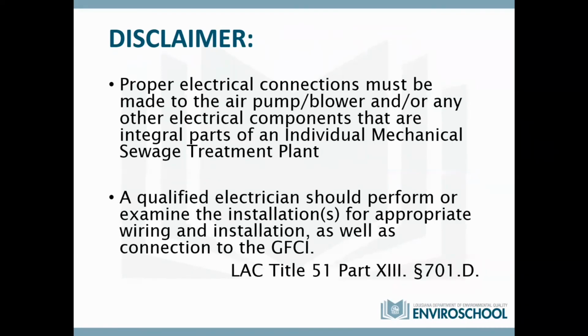And then the Department of Health also says that proper electrical connections must be made to the air pump, blower, and any other electrical components that are integral parts of an individual mechanical sewage treatment plant. Basically, a qualified electrician should perform or examine the installations for appropriate wiring and installation, as well as connection to the GFCI, those outside outlets with the breakers installed on them. And this is where that is specified in the code. So basically, if you get above your head and anything electrical is going on, you have to have somebody that's certified to do it.